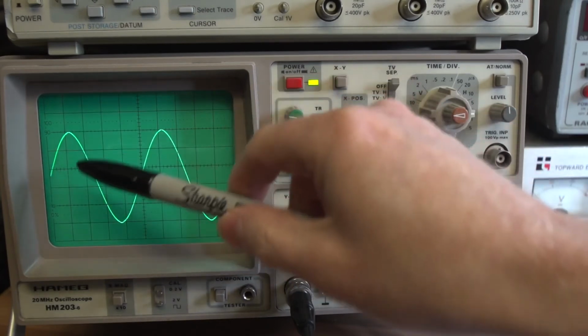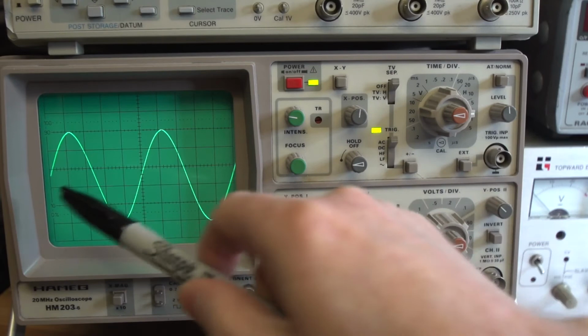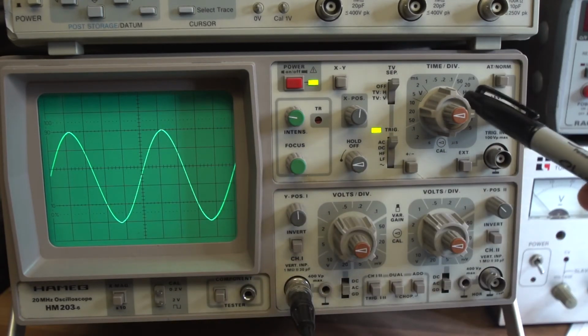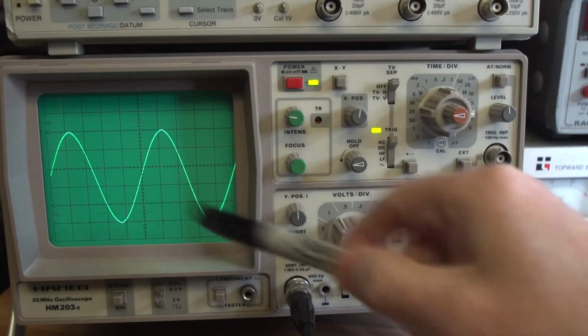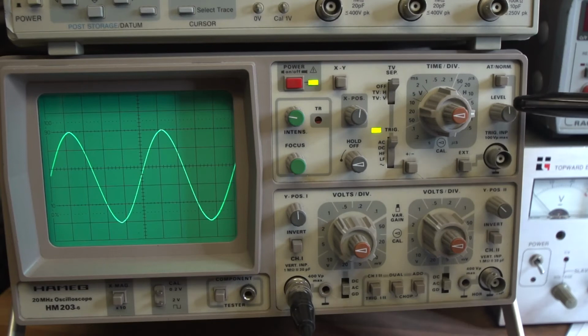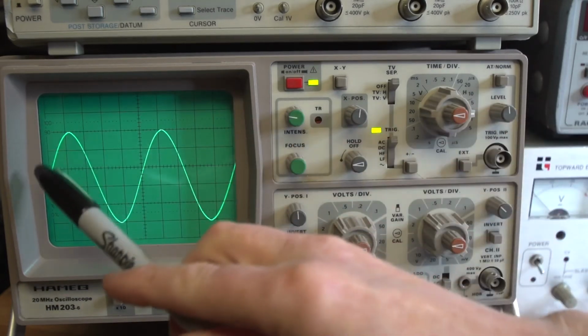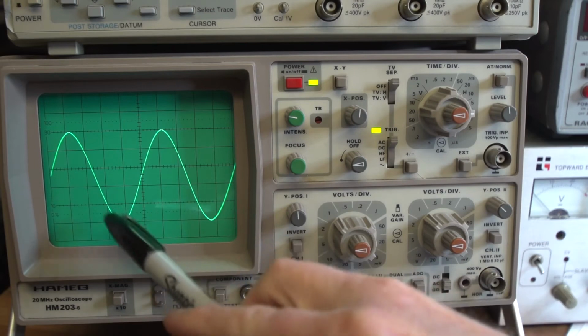It's quite locked. So what's allowing the beam to synchronize to the input signal? What's allowing the time-base control to be exactly correct with the actual input, high and low and high and low? Well, that's down to the triggering, and you have a trigger control on all oscilloscopes. And all that's really doing is sensing when the input level is above a certain point or below a certain point.